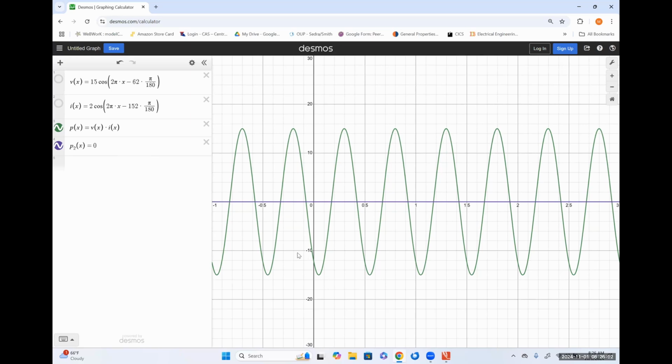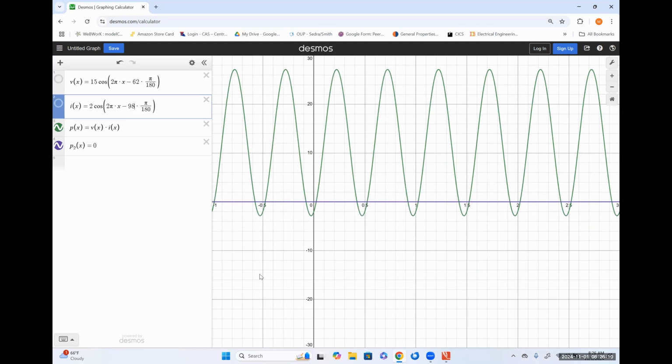So when we go back to, I think I originally had this as like negative 98 or something like that. So if we looked at that generic network originally, where we said that it looked kind of inductive, like when we had a resistor and an inductor in series, notice that our instantaneous power, most of the time, it's positive, but some of the time it's negative. And that some of the time that it's negative is when the inductor is supplying power into the system. So our temporary energy storage elements, like capacitors and inductors, actually pump power back towards the source, okay?